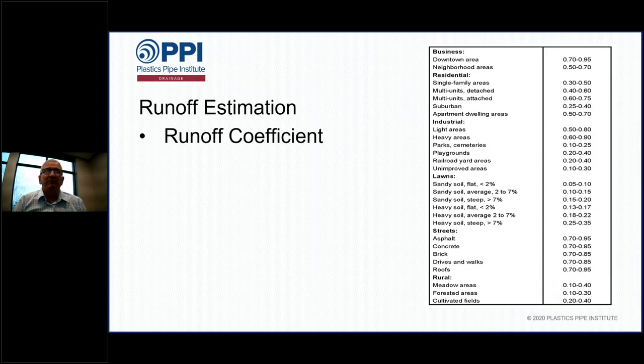And what is our runoff coefficient? It's basically an indicator of how much rainfall is converted into runoff. And it's a single value. For larger drainage areas, you have to start using composites, where if part of your drainage area is paved and part of it's rural, you start using a weighted average of the area for the different runoff coefficients. And the tabular values are available all over the place. There's tons of locations to get these C values.